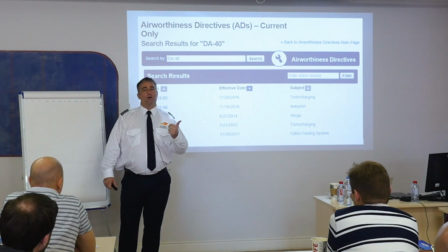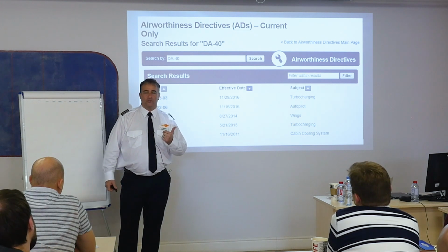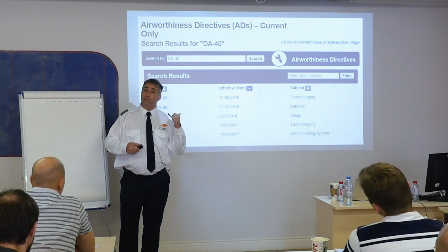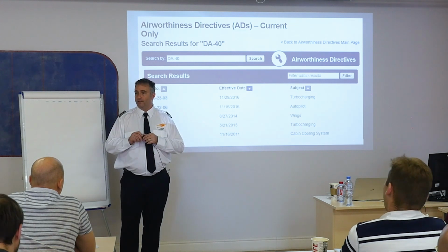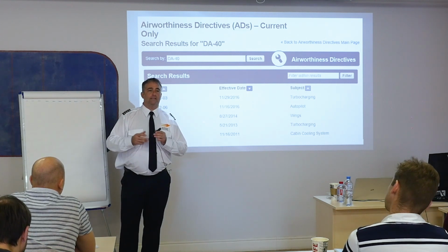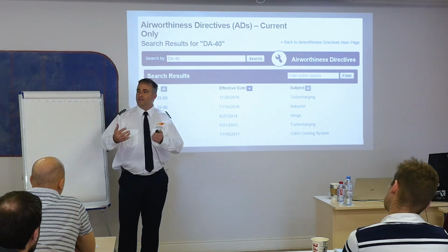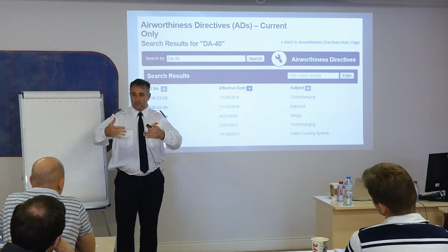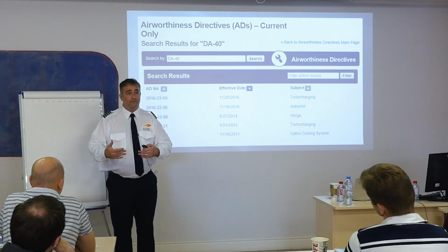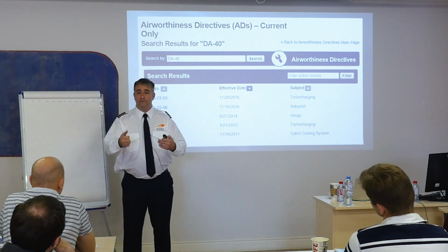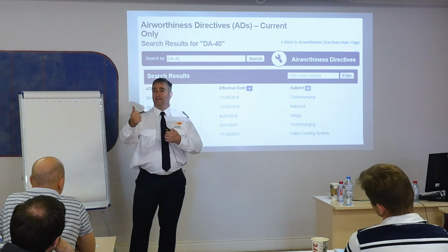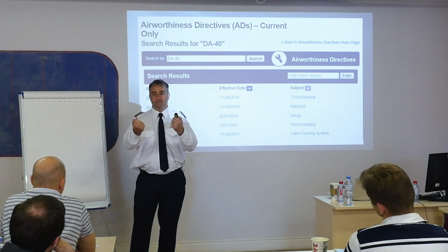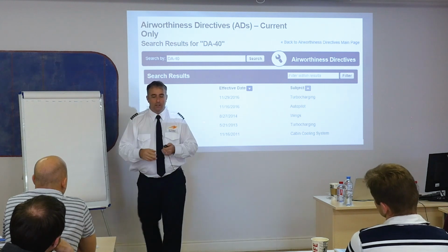With an airplane, it's not called a recall. It's called an airworthiness directive. So it affects my airworthiness certificate. As long as I comply with all airworthiness directives, well, then the airplane is still airworthy. An example of this is on some Cessna 172s, the seat tracks would get stuck. And pilots would think that the seat was locked. And then they would take off, and instead of the seat being locked, they take off, they go like this, the airplane comes up, and the seat goes back. What's the only thing they're holding on to? Control yoke. Ah! All right, so they crash.